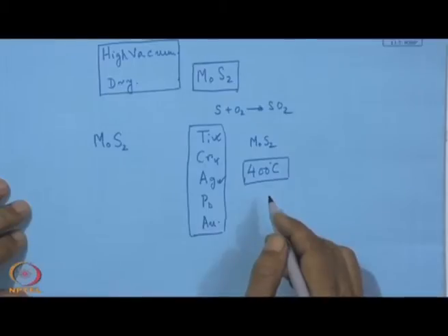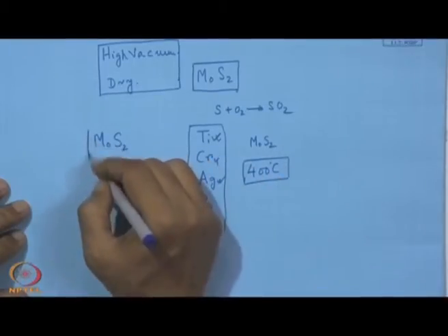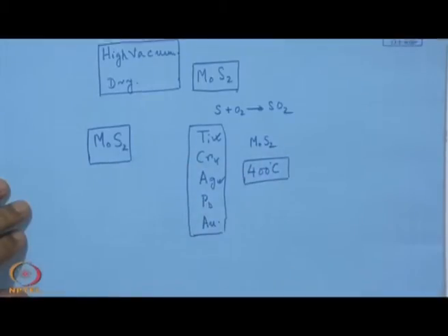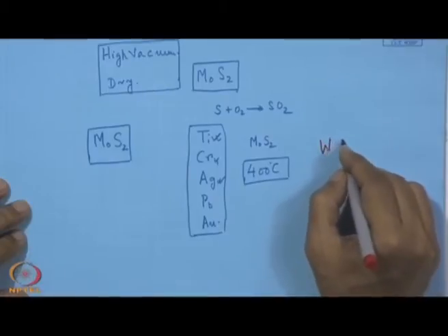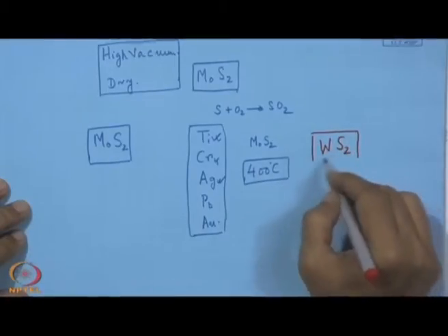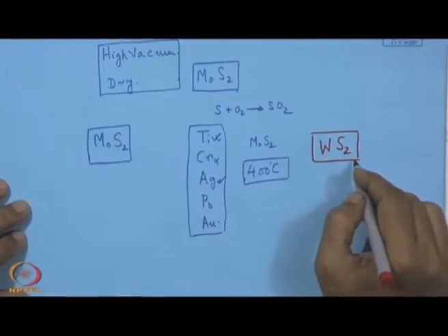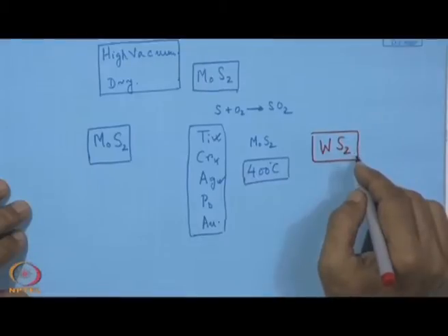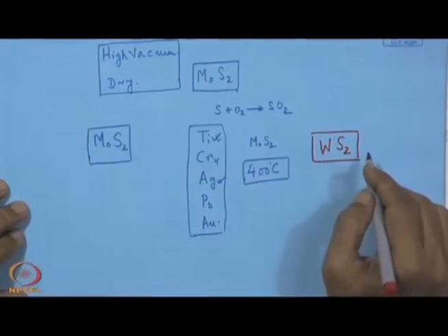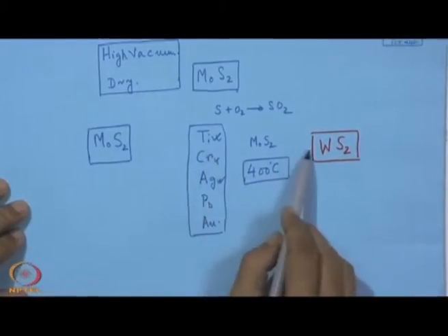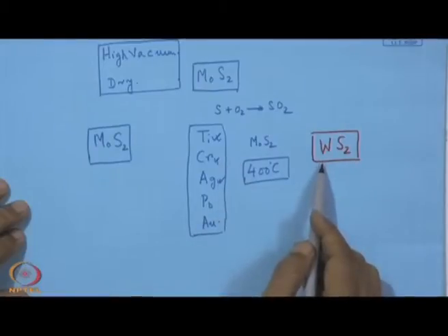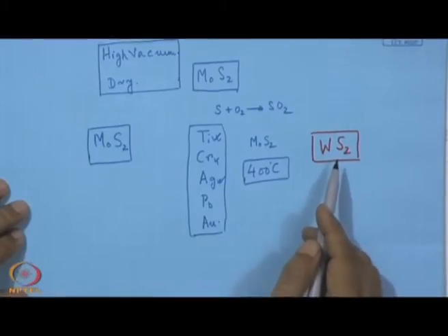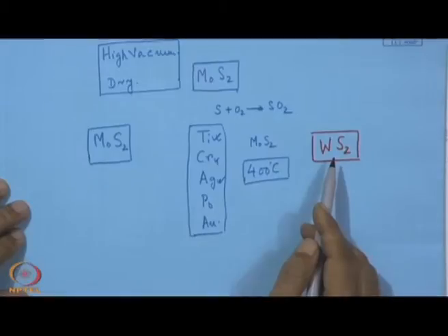And in this respect we can mention that on one side we have MoS2, but also we have WS2, a later addition, tungsten disulphide. This has a capability of holding its stability. It is chemically stable still up to 700 degrees centigrade. That can also be another good candidate, but it has to be seen whether by adding such material we can also augment its property for various fields of application, where we still have to work with a higher temperature or with a higher level of humidity.